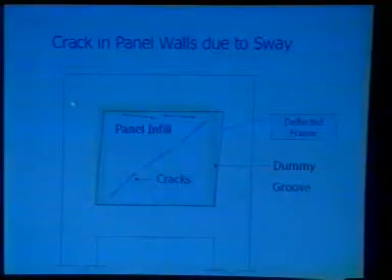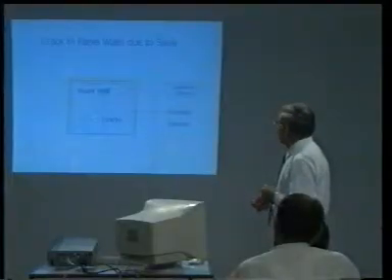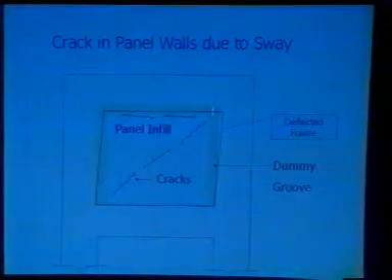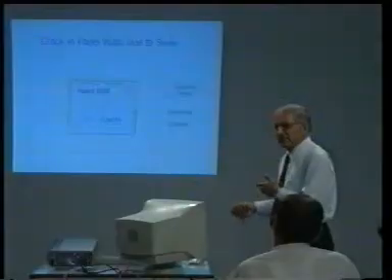A portal frame is going to sway under load, whether it is wind or an earthquake condition. This is going to create shear stress and an extra amount of force from both the sides. The drag forces are going to crack it up like this. This can very easily be avoided by providing a dummy groove all around and filling that groove with a compressible material like an acrylic filler or any other filler which is convenient at that location.